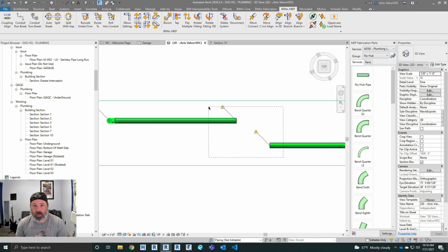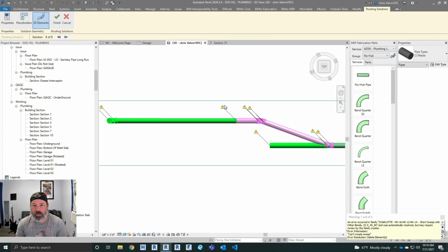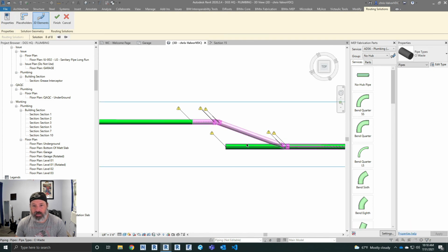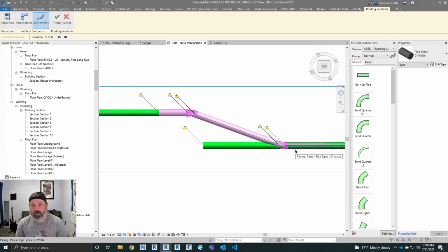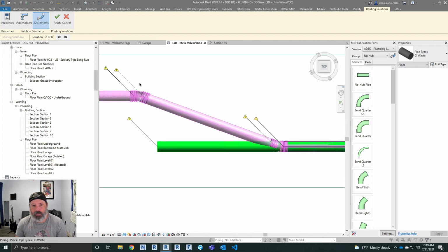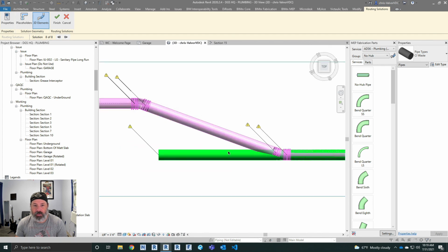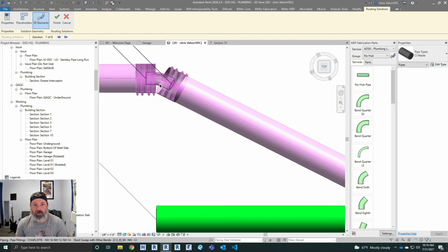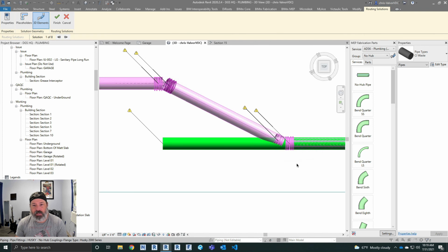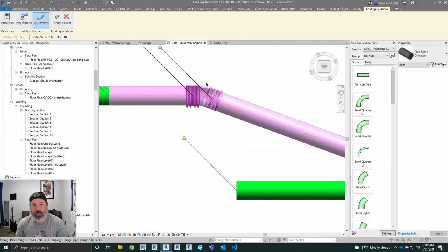So what I normally do is I just select both pipes, and then I come over here to routing solutions, and I hit that, and it's going to give you an error. It's just the way my fitting works. And what it does is it gives you two pipes, and you can see that these fittings are together right here. It shortens this one pipe. And if you go through the solutions, when you look at this now, you can see the fitting is small. That means it's an oddball fitting, but if I go back to the other one, that's an actual 22-degree elbow.